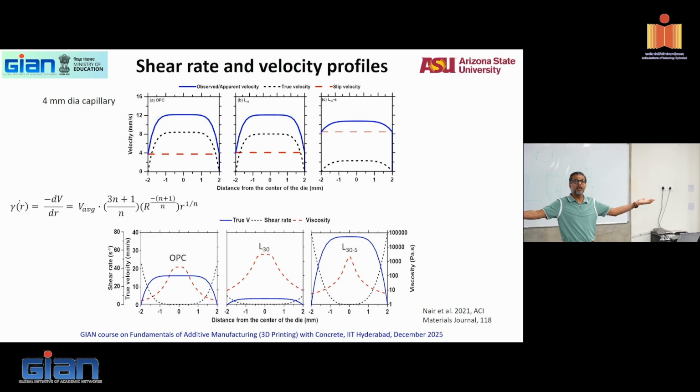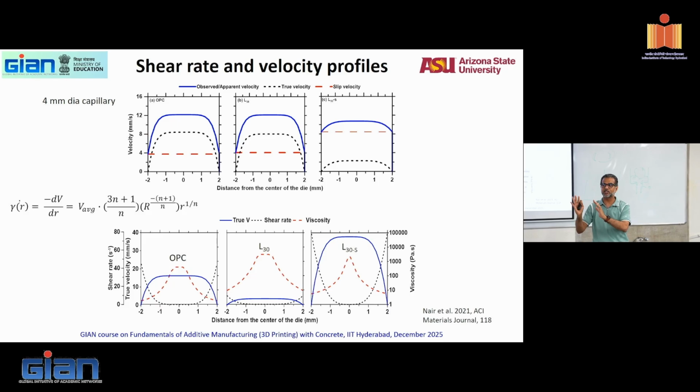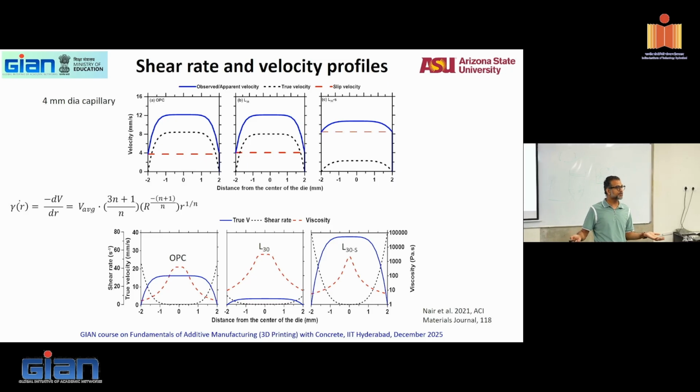You can say, I know my flow through this extruder using this calculation has an apparent shear rate of that. What is now my yield stress? What are now my parameters at that shear rate when I measure in the lab? So it gives you one more place to evaluate, but also helps you to understand how the flow patterns change with different types of material under the same extrusion conditions, same conditions of process in the field.